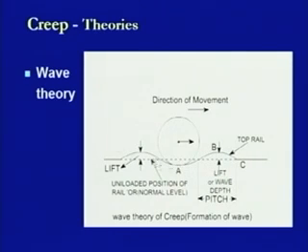So, we have a reverse curve here, and in this reverse curve, just before this wheel section, that is at this location, as well as in the front of this wheel at this location, we are finding that this rail section is going above the normal level of the rail. Now, this is the amount of lift with respect to the normal rail section, whereas this is the amount of depression at this location because of the loading condition due to this wheel.